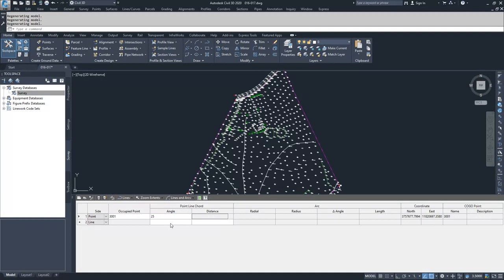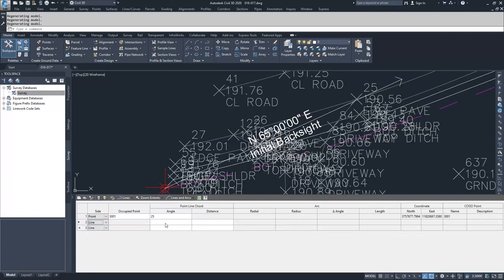If you wanted to move from that traverse start point, you can put in line information. You can also put in another point, so you could traverse to a specific point. You can do a chord arc, a radial arc, or a side shot. I'm going to do a line, and then my next will be a chord. Actually, we'll do a radial.